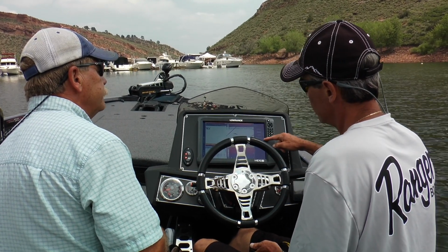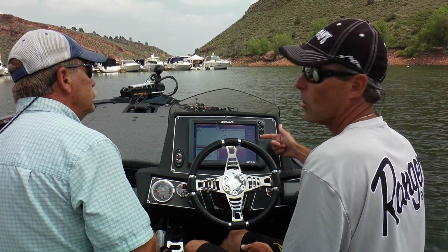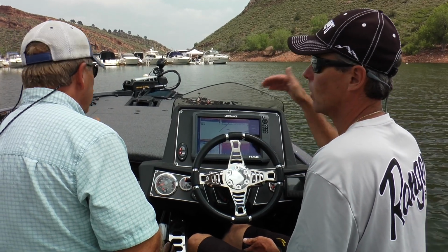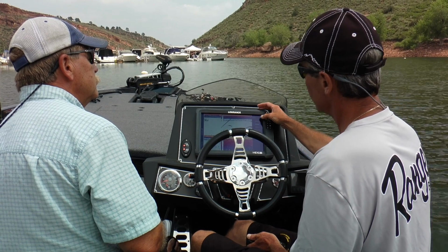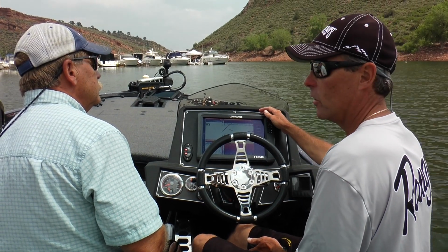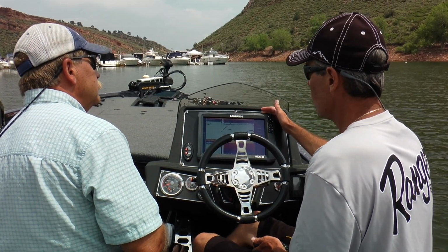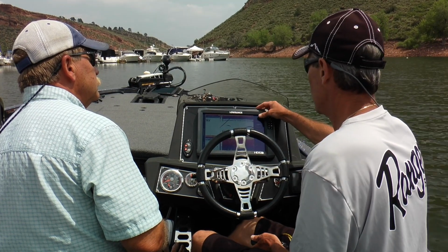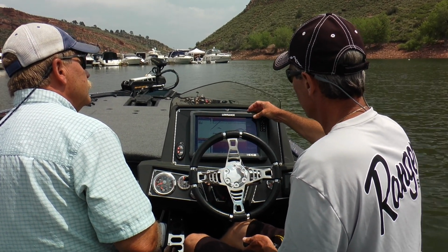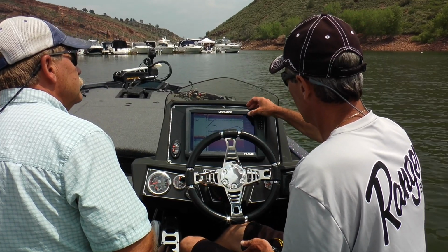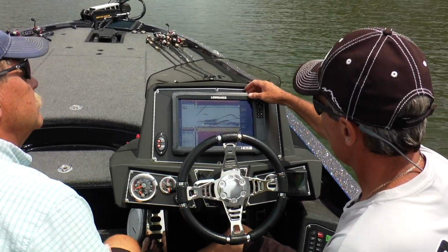And chirp, any of these chirps that you see right here, guys, it's a conglomeration thereof. And so basically we'll run a sequence at different kilohertz, and that's what that's going to be all about. The bottom line is 83 and 200 are the most common ones you're going to use in freshwater. I use 200 most of the time unless I'm in real shallow water. And would you agree with that? I agree with that. Okay. So let me set this back at 200 since we're here. And we'll go back to here.